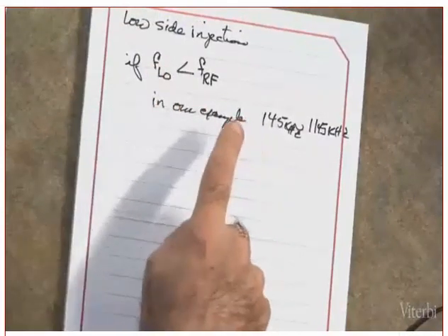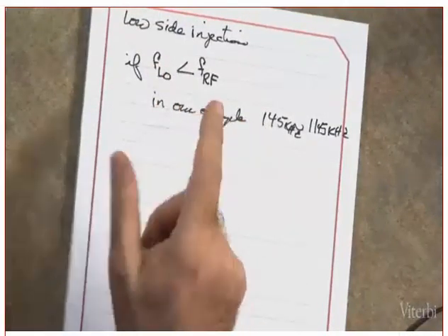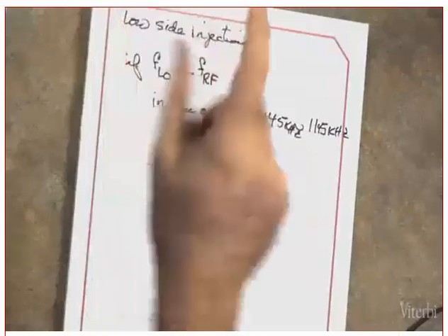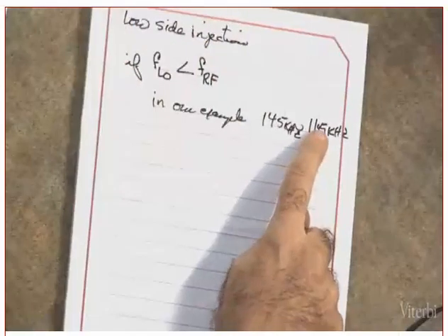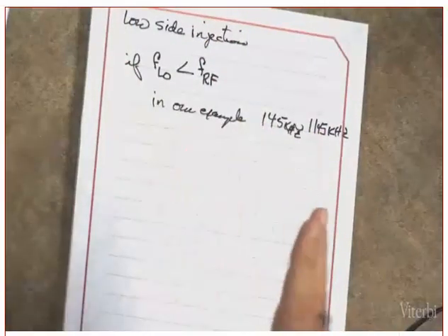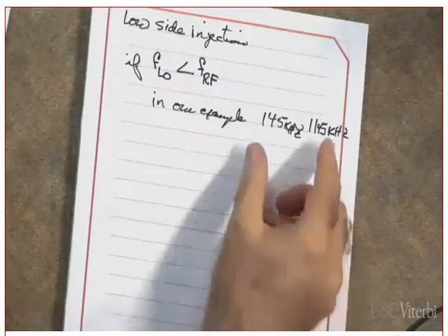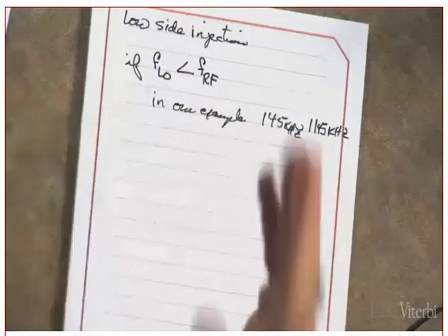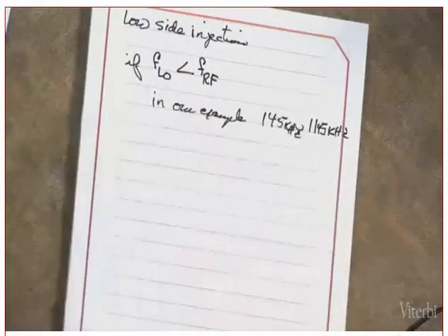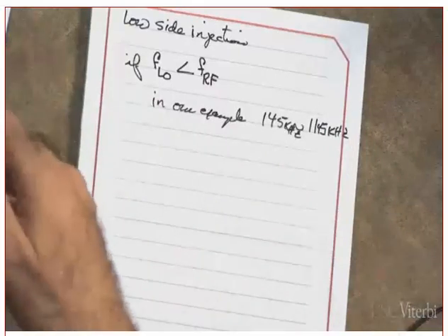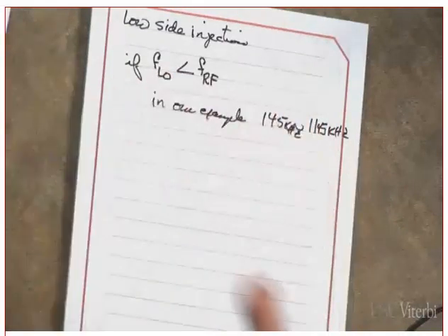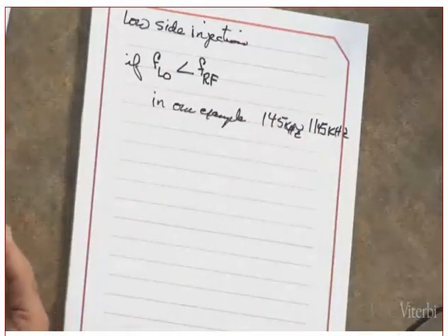However, this one results in a harder design of your VCO, because the ratio between the highest and the lowest is high. The dynamic range is high. By the way, the bandwidth is the same, but the generation of frequencies, the highest minus the lowest, or the highest divided by the lowest, the higher it is, it's harder to design the mixer. Clear? Okay. But I will show you that shortly when we get there.